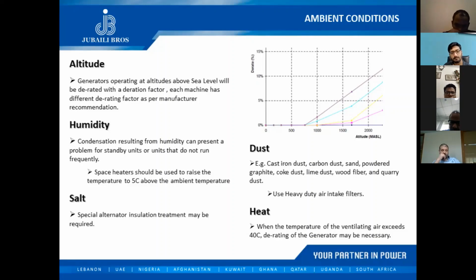With a higher temperature, again, back to the air density. The higher the temperature, the lower the air density. The lower the air density, the less air is going into the burning chambers, so the less power output my engine is giving me. Okay.